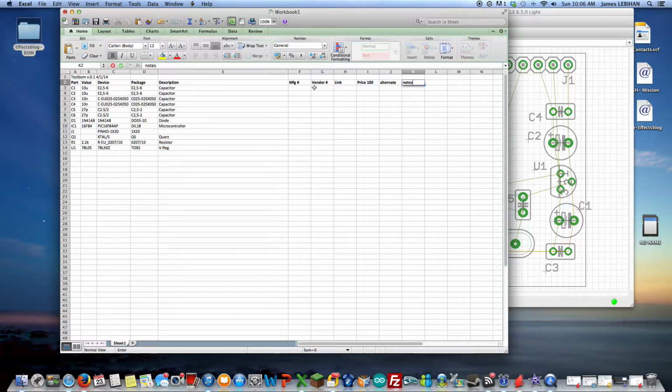And that's different to the vendor part number, which is the part number from where we buy it from. So if it's a Panasonic cap, it'll be Panasonic's number in here. If we go buy it from Allied Electronics, for example, it will be the Allied Electronics number in here for this particular part. And the reason that we have both in there is that I need the part number from the vendor in order to order the part. So when I go place a PO, I'm going to need that number right here with the vendor to order the part. The manufacturing number I need to identify it specifically and to send to other vendors.